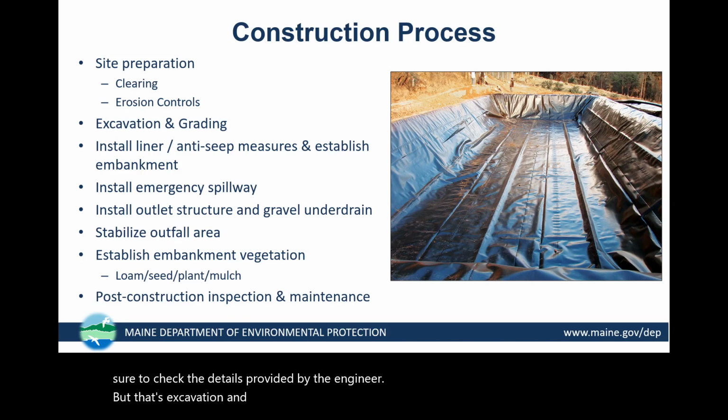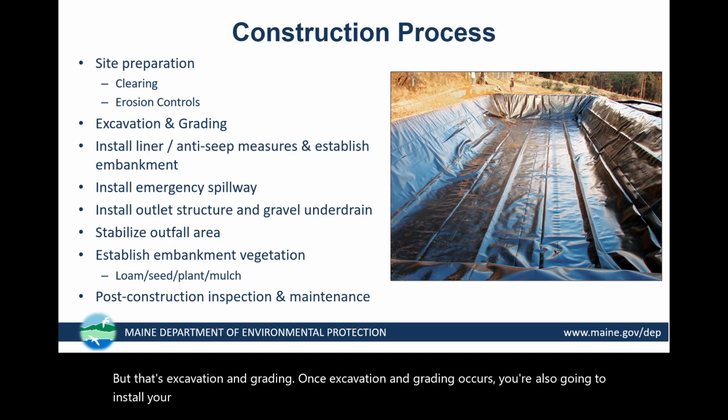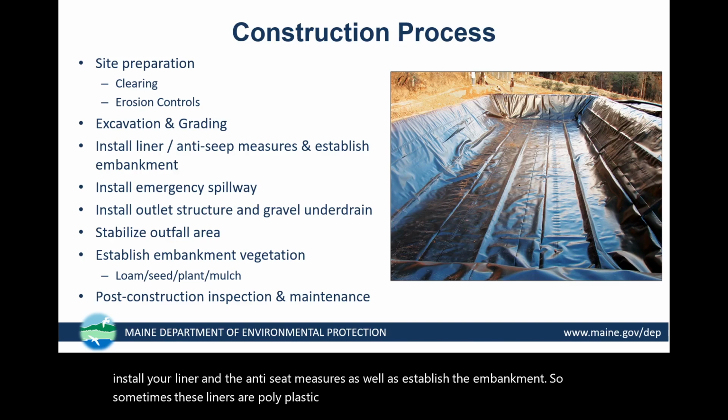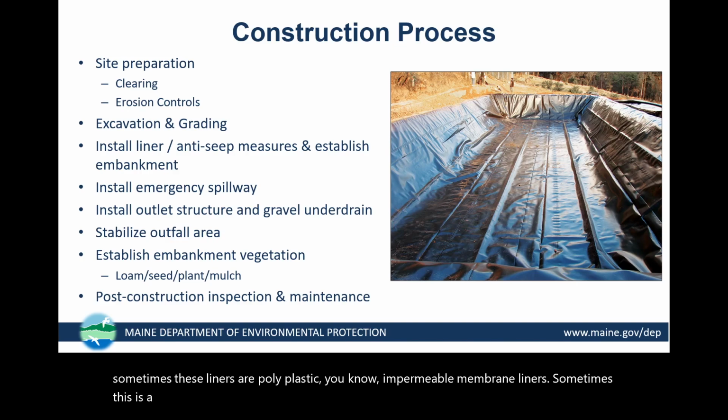Once excavation and grading occurs, you're also going to install your liner and the anti-seep measures, as well as establish the embankment. So sometimes these liners are poly, plastic, impermeable membrane liners. Sometimes this is a compacted clay liner.